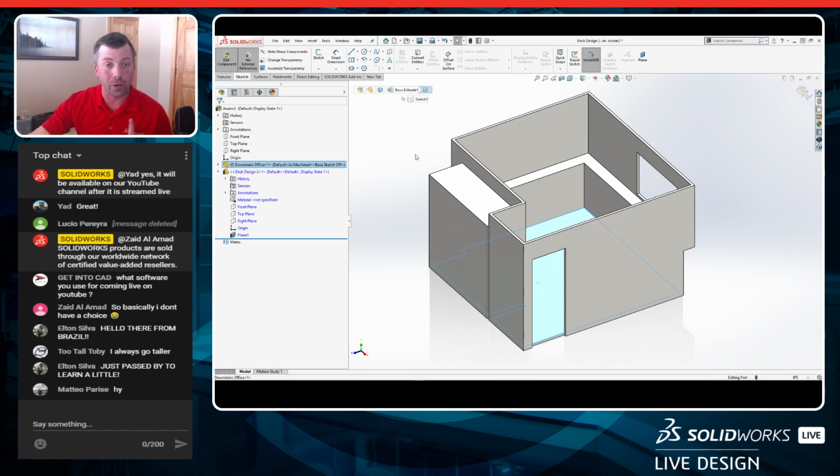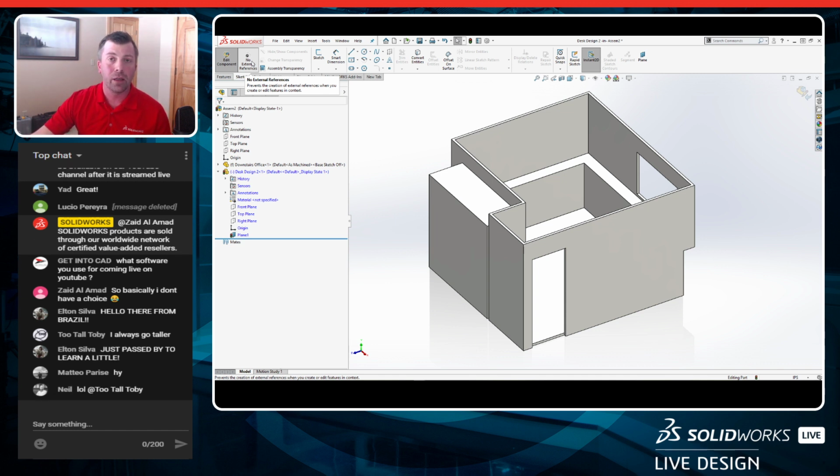What you can do, and here's a really nice trick, is up on the top as you're working and editing in these assemblies, there's a button, this no external references, and you can turn that on. What I'm telling SOLIDWORKS is, hey, even if I reference something else, don't make the connection. Don't actively save that reference in there because I maybe don't want it.